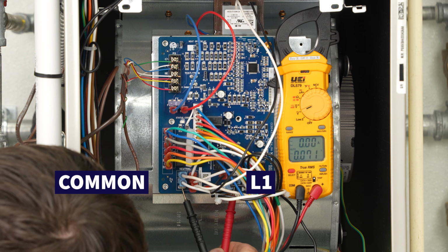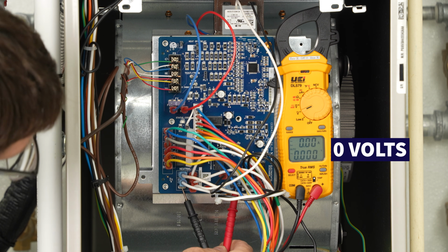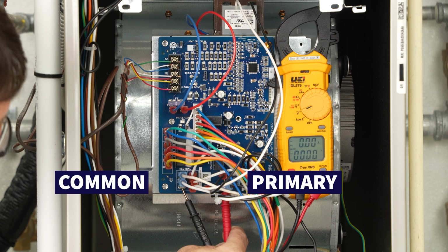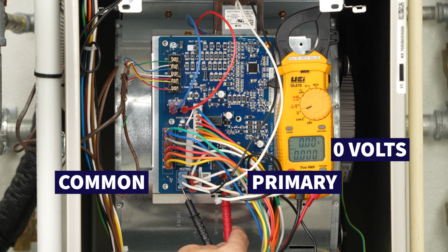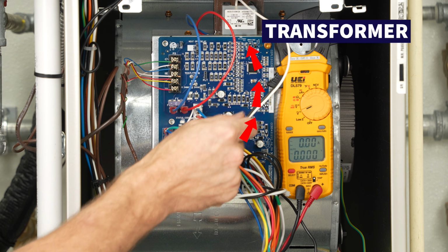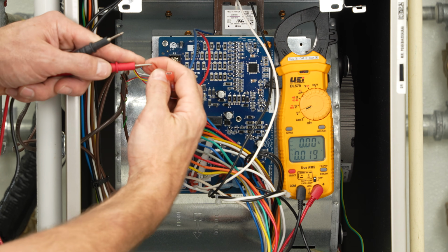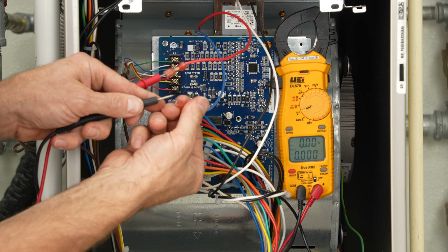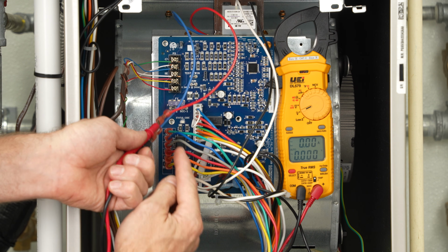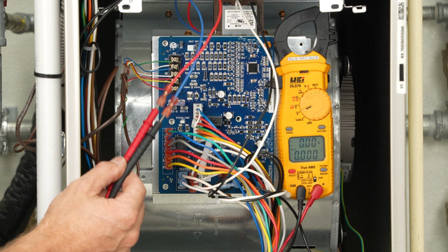And so we can measure from point A to point B, and as you can see right now, we have 0 volts, and so that's L1 in common. If we did have voltage right here, we would then need to go to the primary in common. And once again, we have 0 volts because the primary in common is heading over to the transformer, and basically we want to see if this is getting fed with 120 volts of power. And the other thing is we can measure the 24 volts by just taking our probes right here into the ends. Now, we're not sticking them right into the spade terminals, we're sticking them between the plastic and the spades. And so with our power right here, we want to see if we're measuring 24 volts.